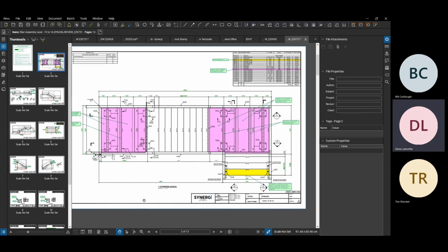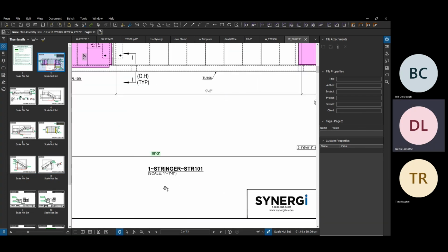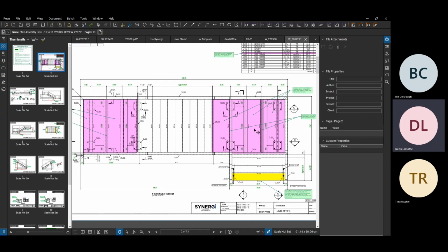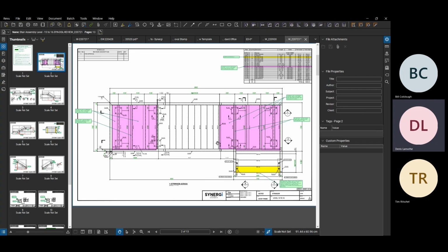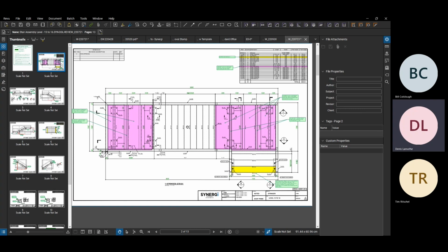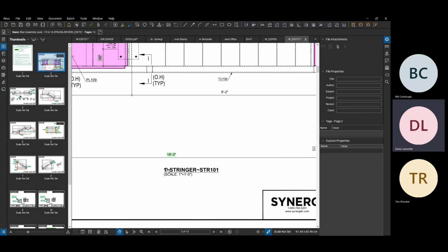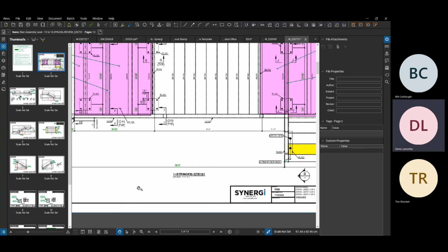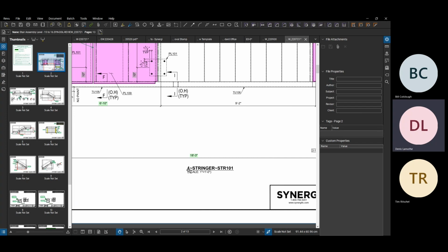We check that the quantities are accurate. So in this case here, there's just this one stringer assembly. If we had multiple floors and all these landing to landing sections here were identical, and by a stroke of luck, all the floor to floor elevations on site were the same, they match on each floor, then you might see here on the assembly that your quantities will change to show more parts if it's required. If we have 4 floors and everything matches perfectly, then we should have had 4 assemblies of this type. So check the quantities and make sure that they match.